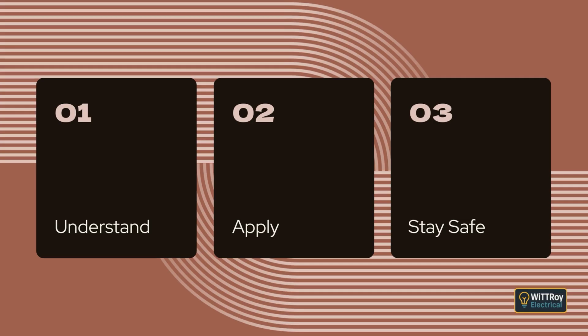When current carrying capacity is taken from NZS 3008.1, we must use a reference ambient temperature of 30 degrees for New Zealand for cables in air. For cables buried direct in the ground or underground conduits, the reference ambient temperature for New Zealand is 15 degrees.